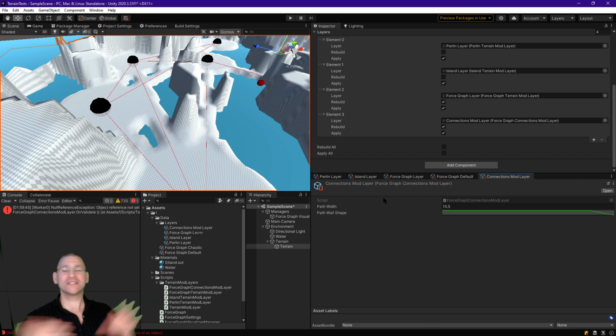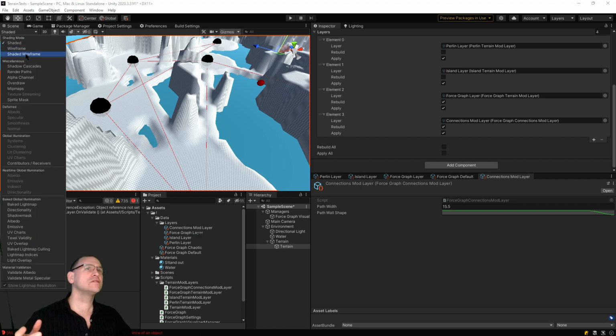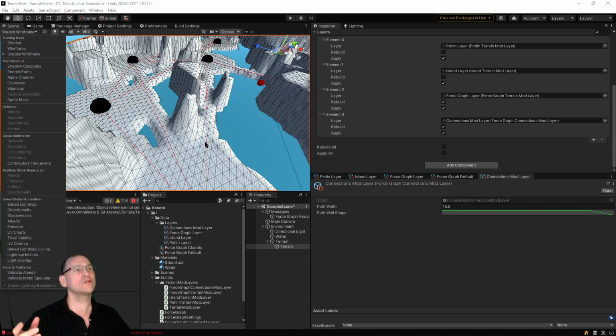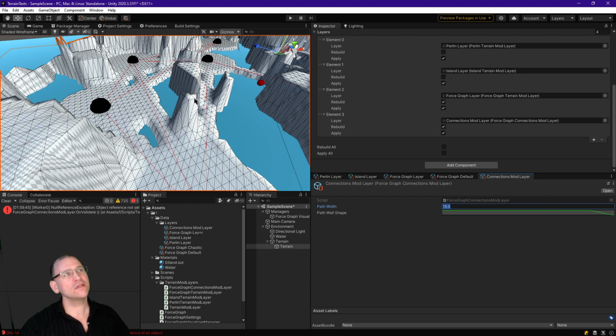Now, on this terrain, which is 1,000 meters wide, its height map resolution is 129, which basically means each one of these is about 8. It's about 7 or 8, 8 or 9 units across, or meters across from one height point to another. So back to this one. Between this spot to this spot is about 9 meters. Okay, so it's pretty large. That means at 15, we're really only going to see about 2 to 3 of these get separated out.